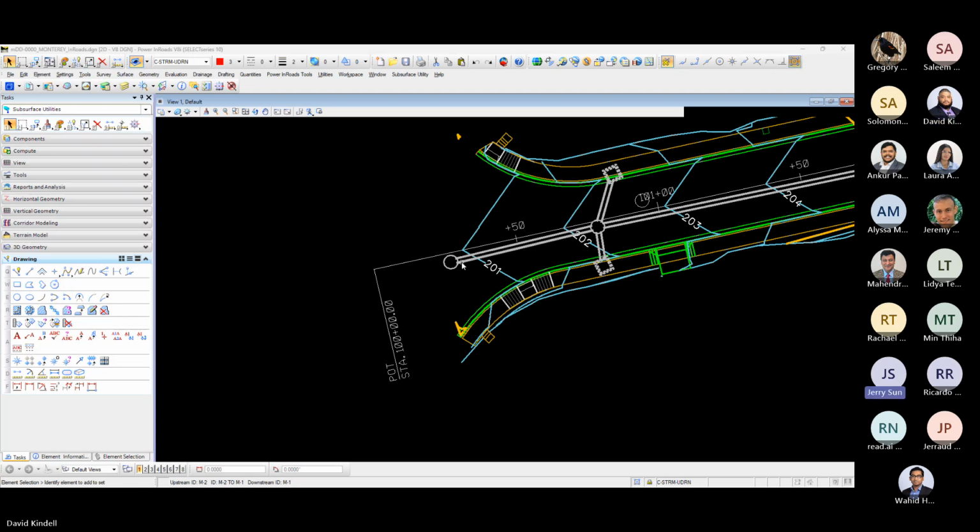Basically, if you set up the invert based on the structure, it will be very confusing. You set up the invert based on the slope for the pipe. For example, you collect the pipe and you know the invert in, out and slope.